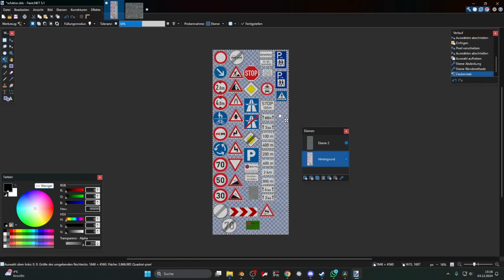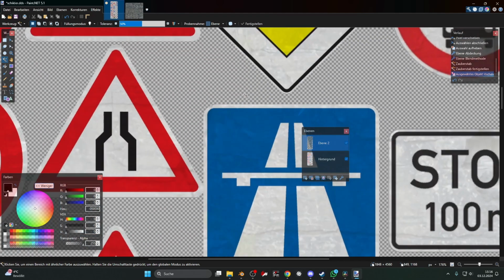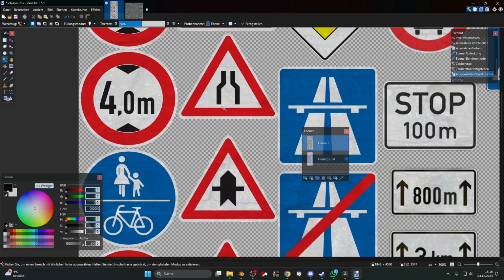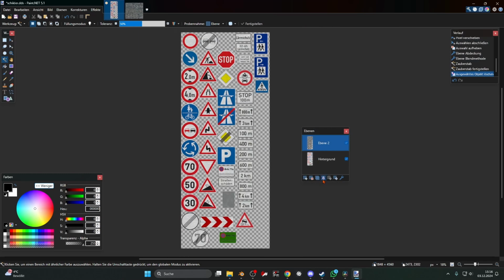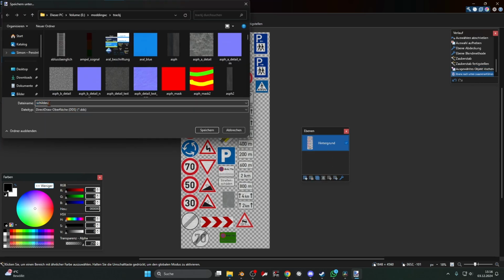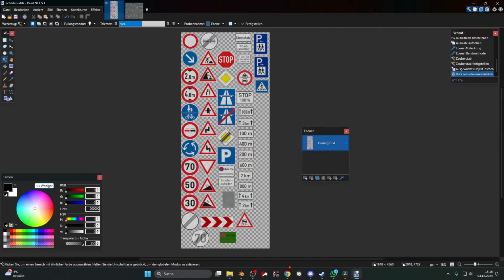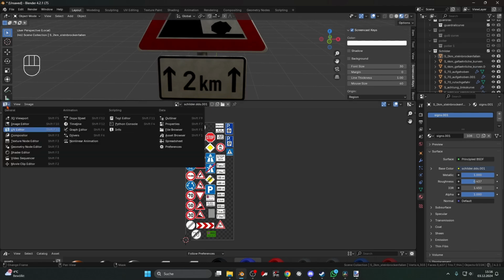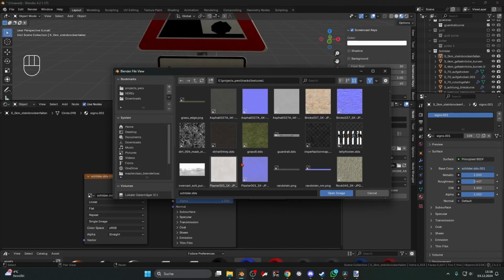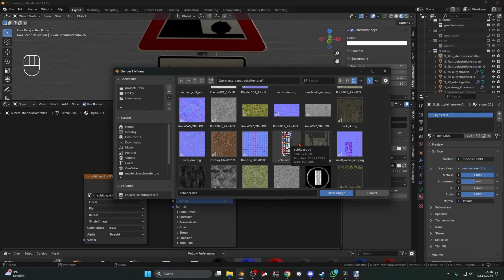And we'll also select the alpha channel, so we still have an alpha, and delete this right out of here. And now these are dirty and unique. Now I can merge them down together and save them as a DDS. Back in Blender, I go to the shader editor and replace this with our new ones.